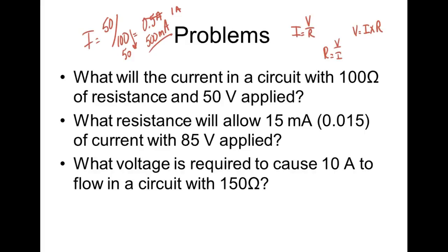1. If I come up here and double the resistance, then I would go down to 0.25 amps, because they're inversely proportional. So now I understand that if I double the opposition in a circuit, the current is going to be half. If I halve the opposition in a circuit, the current is going to double. Right? You understand?